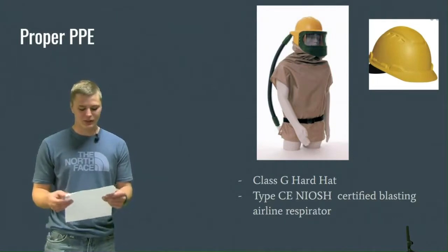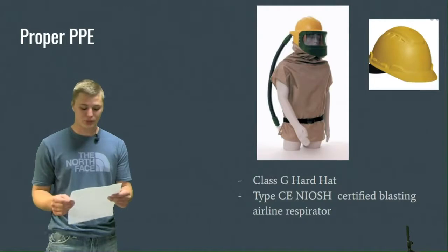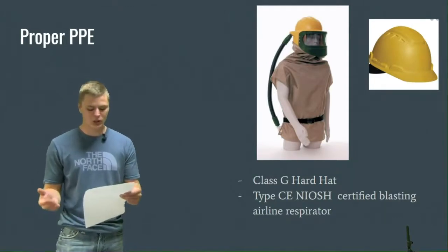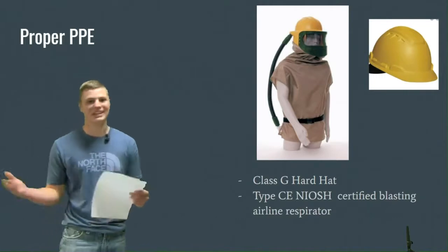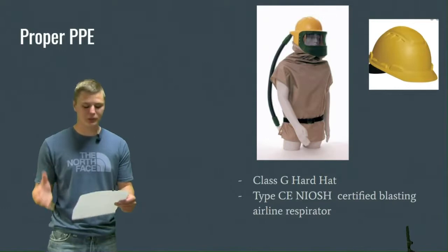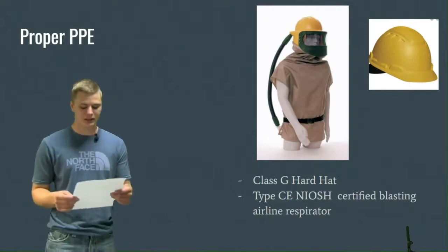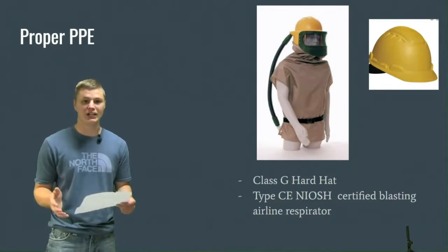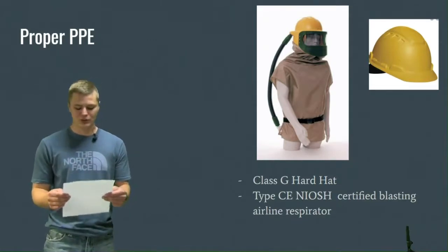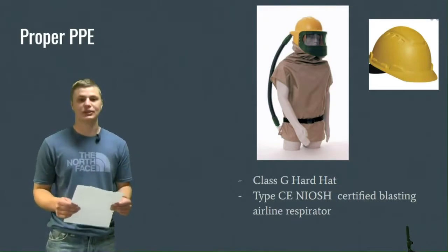Now this is very important because it can keep you from inhaling lead, silica, coal slag, copper slag, glass, and etc. These materials can cause severe damage to your lungs when inhaled and can lead to the loss of lung function and even cause cancer. It is very important for you to have the proper respirator secured and sealed to your person.